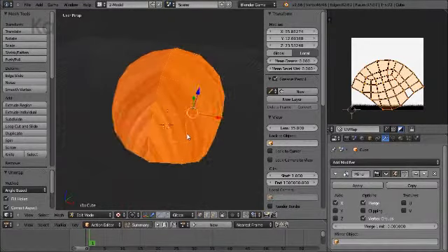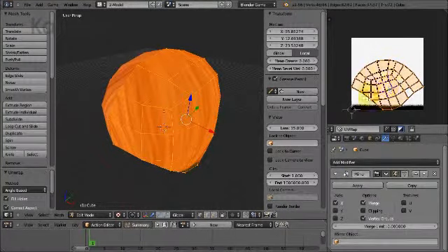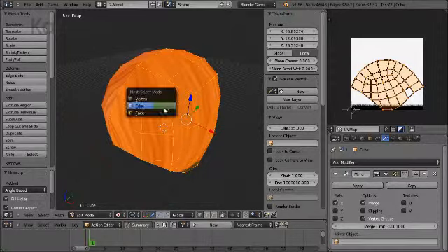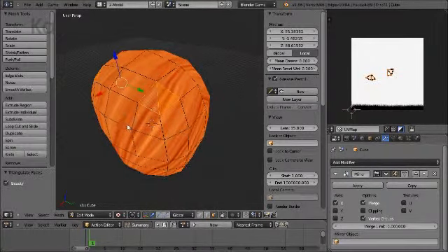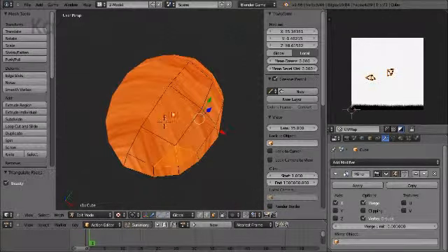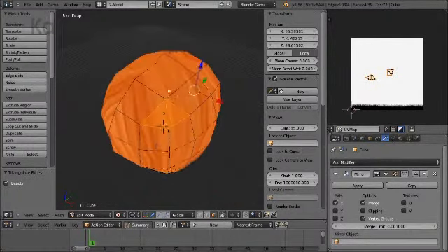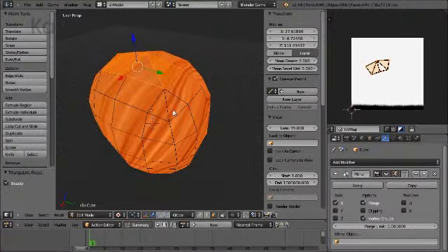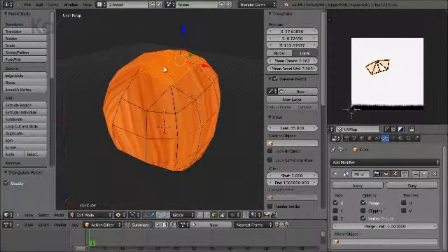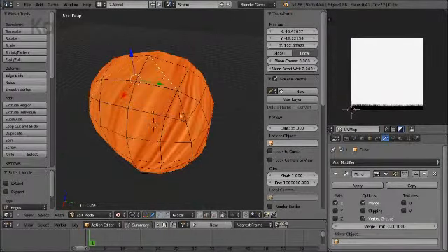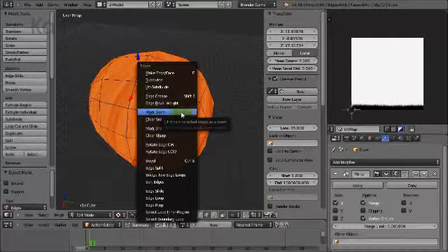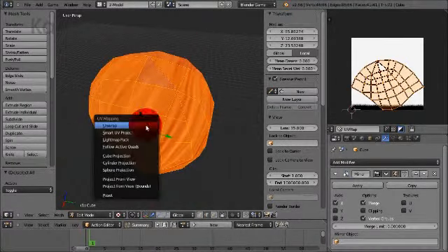But this can be used to then decide how we chop up or seam mark the mesh for better distribution of the texture. So we select a number of different surfaces which may need to be triangulated, that's Control T, in order to expose the internal or diagonal edge along which a seam can be placed. So what we can do is mark a number of edges as seams, UV seams, and unwrap again.